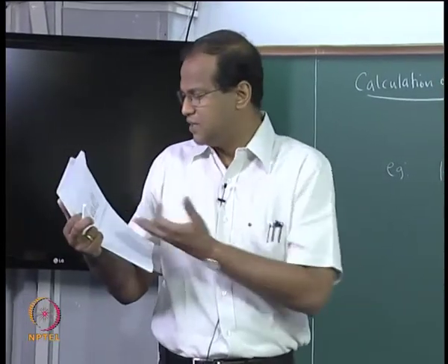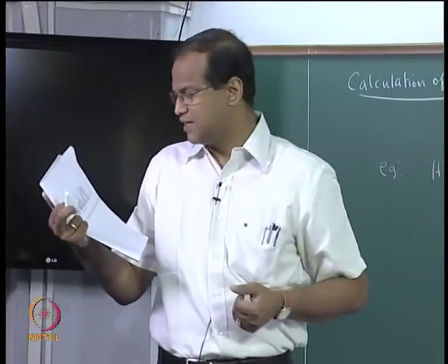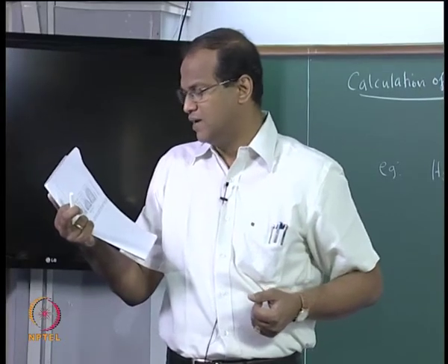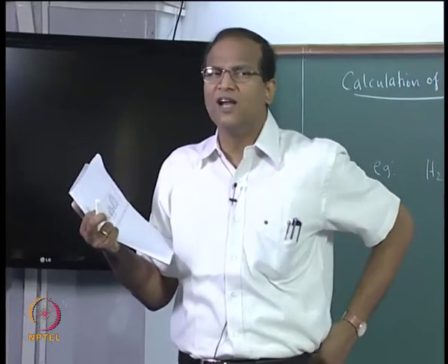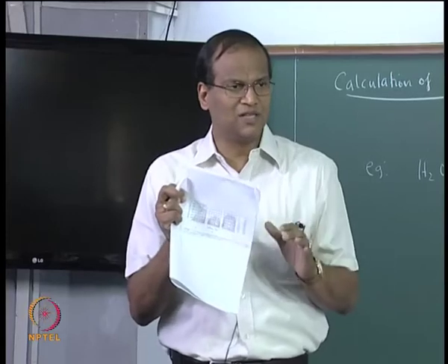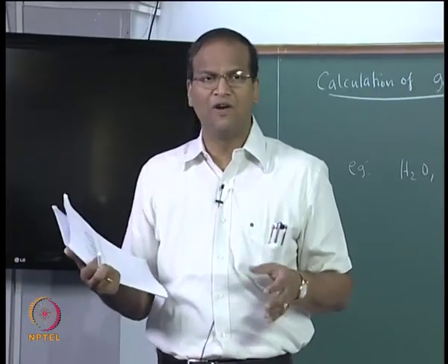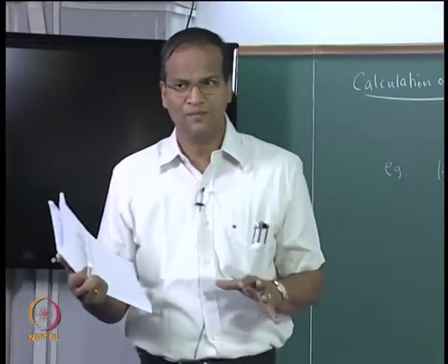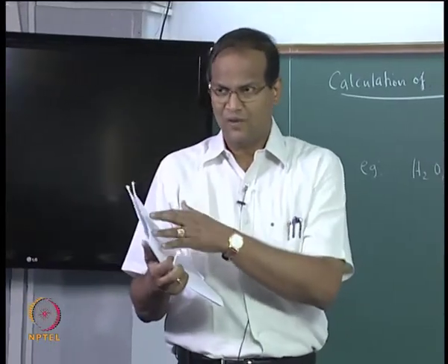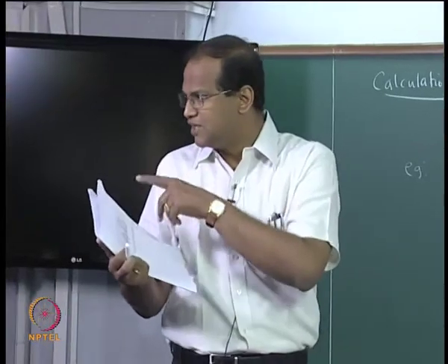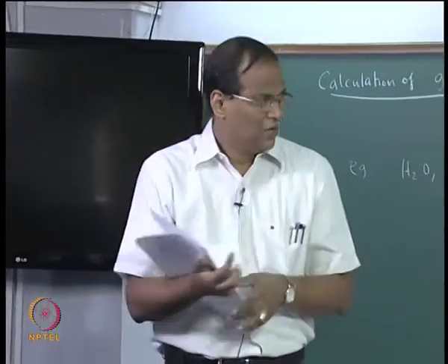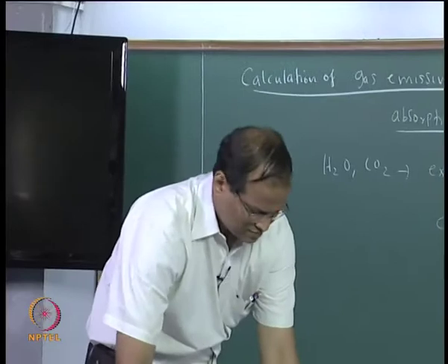What are the 3 temperatures for which correction is available? 400, 810 and greater than 1200. So if I give you greater than 1200, straight away use the third chart. Suppose I say the gas temperature is 650 or 945, 950 Kelvin, then you are in trouble. So you have to read from both the charts and interpolate. So finally epsilon g.